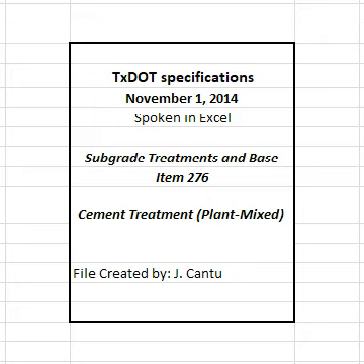2.2 Flexible base. Furnish base material that meets the requirements of Item 247, flexible base, for the type and grade shown on the plans, before the addition of cement. 2.3 Water. Furnish water that is free of industrial waste and other objectionable material. 2.4 Asphalt. Furnish asphalt or emulsion that meets the requirements of Item 300, asphalts, oils, and emulsions, when permitted for curing purposes as shown on the plans or as directed.